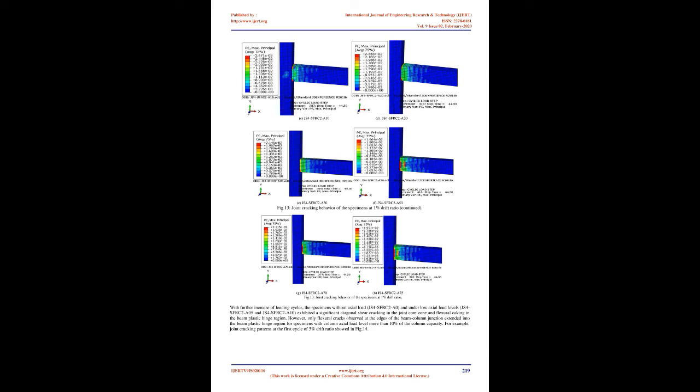Based on the amount of axial load ratio, these 8 specimens are designated as JS4-SFRC2A0, JS4-SFRC2A05, JS4-SFRC2A10, JS4-SFRC2A20, JS4-SFRC2A30, JS4-SFRC2A50, JS4-SFRC2A70, and JS4-SFRC2A75, respectively. The column and beam cross-section, length and reinforcement details are identical to the validated specimen, JNR2BTR, except the number of stirrups in the joint panel zone.